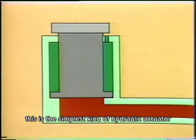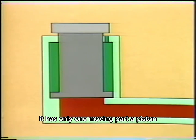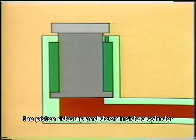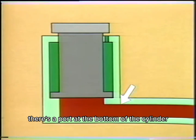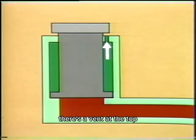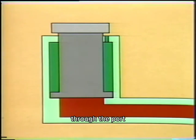This is the simplest kind of hydraulic actuator, single-acting, load return. It has only one moving part, a piston, which is acted upon by a fluid under pressure. The piston rides up and down inside a cylinder. To admit hydraulic fluid, there's a port at the bottom of the cylinder. And to relieve air pressure, there's a vent at the top. The actuator is usually operated by controlling the direction of fluid flow through the port.